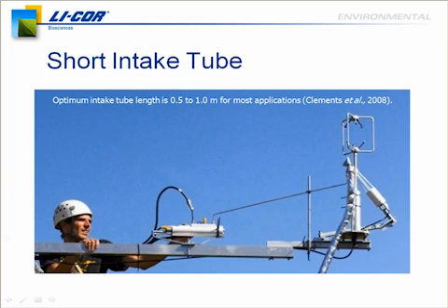And what they found out is if the tube is too short, the temperatures will not attenuate. However, if the tube is too long, then the H2O fluxes will attenuate. And so this can happen with tubes that are a 1+ meter, where you start to see H2O fluxes being lost, and you can even see CO2 fluxes being lost if the tubing is up over 10 meters.